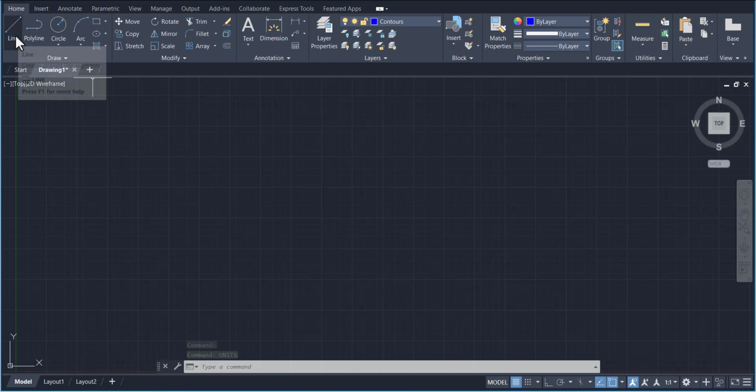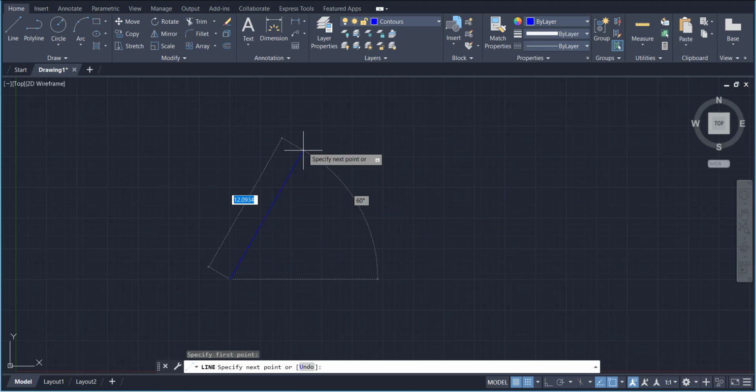So first I am going to draw a line. I am going to activate this snap grid option. I am going to select the line tool. So now my cursor is snapping with this grid. So here will be my first point, and now you can see I can move my cursor here and the line is in slope. I'm going to uncheck this snap option, and here we have this option which will only restrict our cursor to horizontal or vertical, meaning 90 and 0 angle.